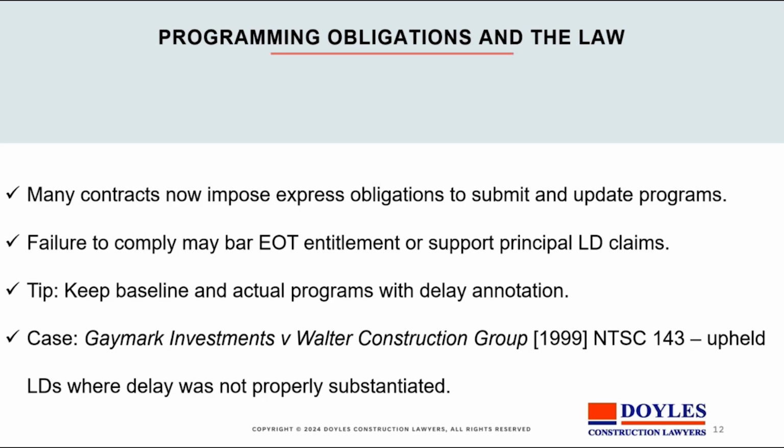If he's given a result of those pretty quickly, that is within, say, 5 days or something, he can easily adjust the program in order that he has a clear basis on which to submit the next EOT. But if that decision doesn't come back, he then has very complex situations where he has to adopt the base program with his first claim not approved, or the base program with his first claim approved, and then develop the basis for his second claim.